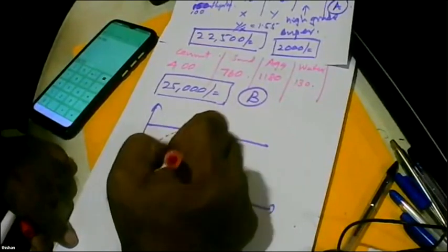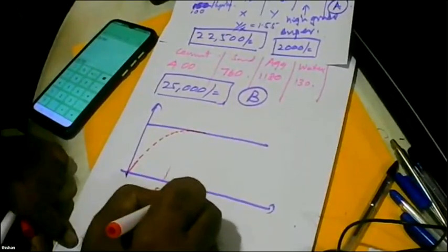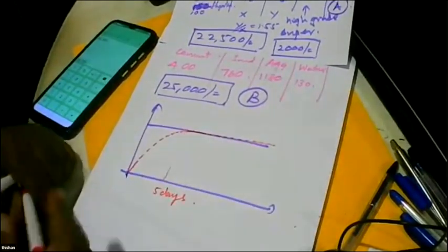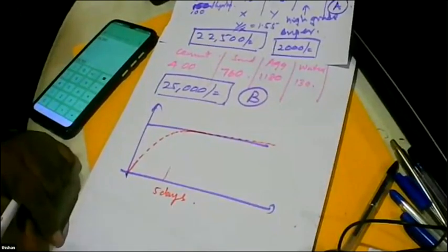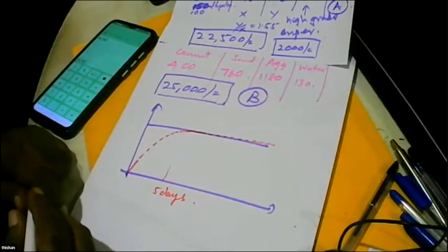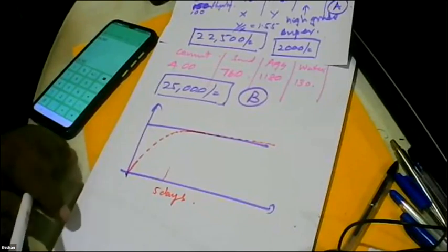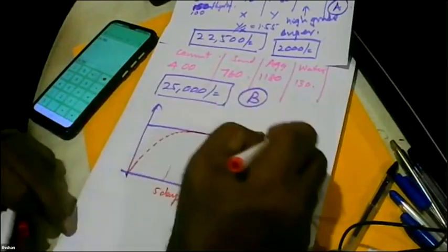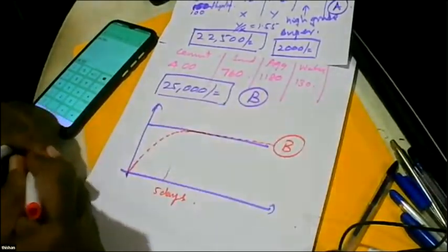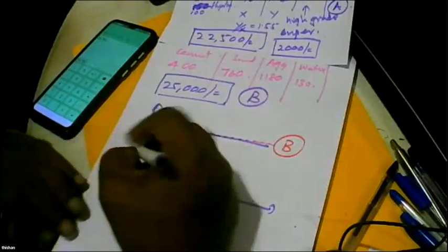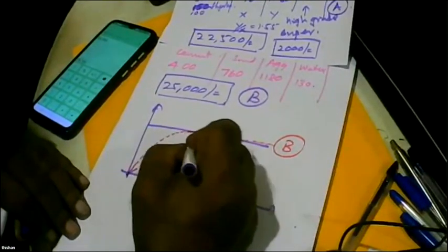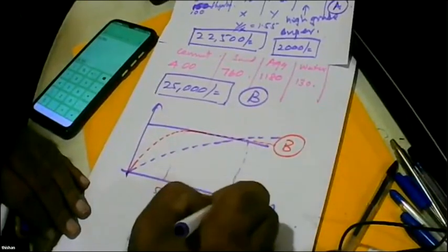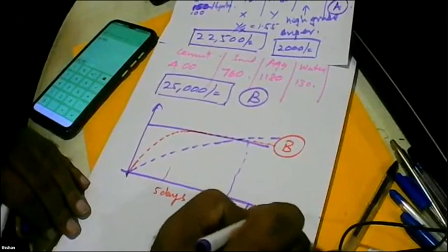After about 5 days, you find now it has reached the full strength. But now it is going up very slowly, because after about 2 weeks, all tricalcium silicate reactions are over. So now it's going up very slowly. Now this one, that is mix B. Mix A is much slower. It goes like this. But before 28 days, it also goes above the requirement.